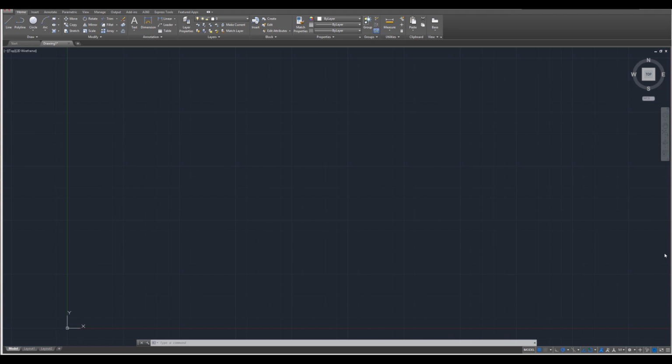So a plot can be used for floor plans or for mapping out terrain and a number of other things, and we can usually do them with an absolute or a relative coordinate system. To get started, open up a new AutoCAD file, and let's first start with absolute coordinates. Absolute coordinates are going to be based off your grid spacing.